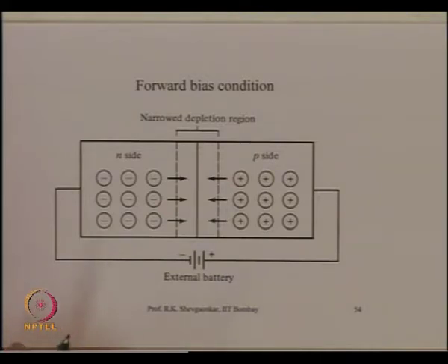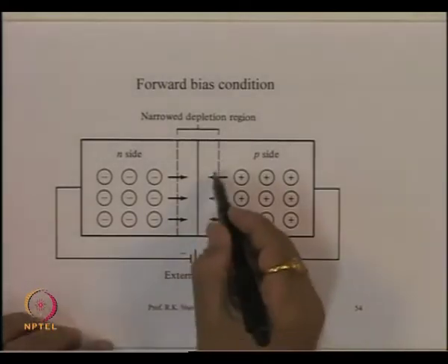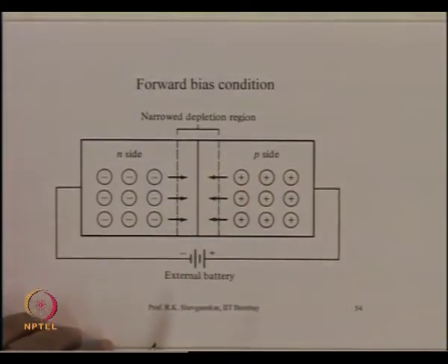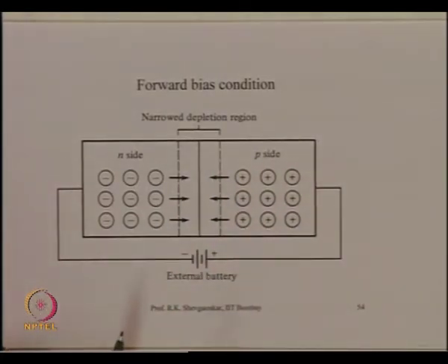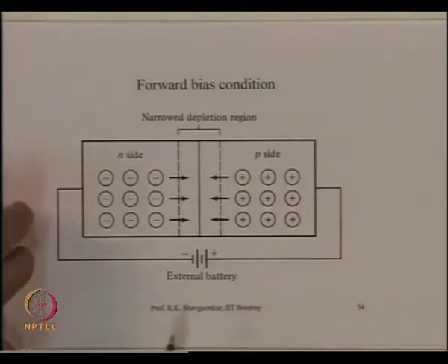And the easiest way of doing that is essentially creating what is called a p-n junction. If the p-n junction is forward biased, then the electrons and holes are injected into the depletion region, they recombine in the depletion region, and the recombination of the electrons and holes may produce photons.